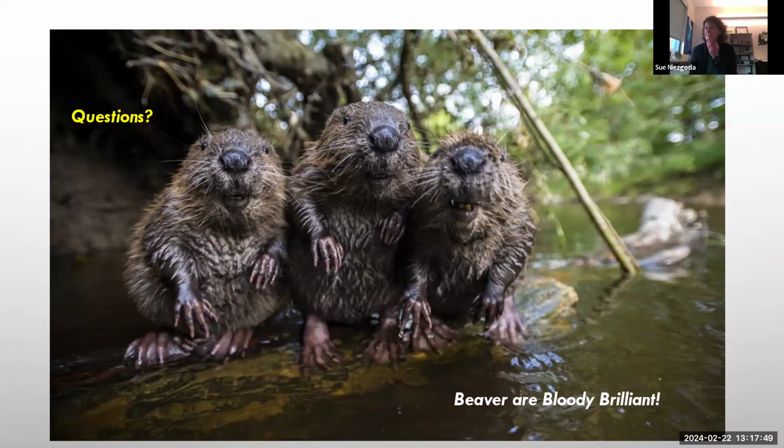But that process is important, and right now we're learning, but once again, we've only had them in the ground for 2 years. The ponding process is really what's important. It's creating the pond for the sediment to fall out, and to retain that sediment with the phosphorus, because the beaver dam analogs themselves do not filter phosphorus out, right?